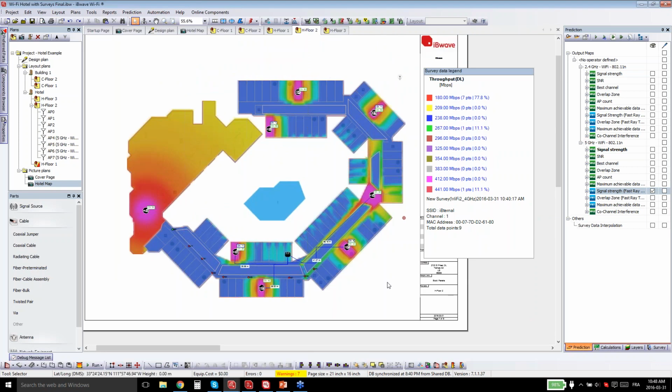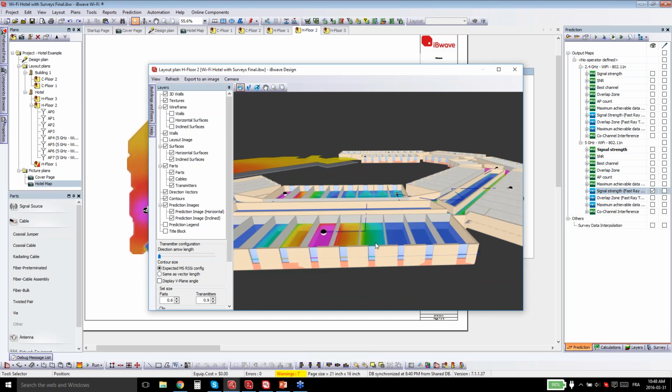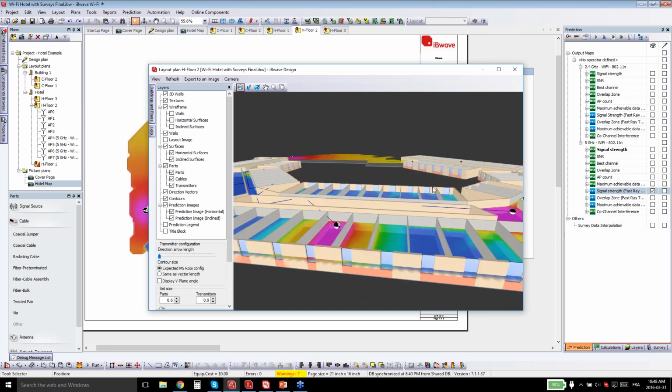So we've done that prediction, and again, I used what we call the fast ray tracing prediction. This is the 3D prediction, the blue one. If we wanted to do a two-dimensional prediction, we have a different way of doing that. And what does it mean by two-dimensional prediction? So right now I just showed you here in 3D, we modeled all those walls according to their wall heights.